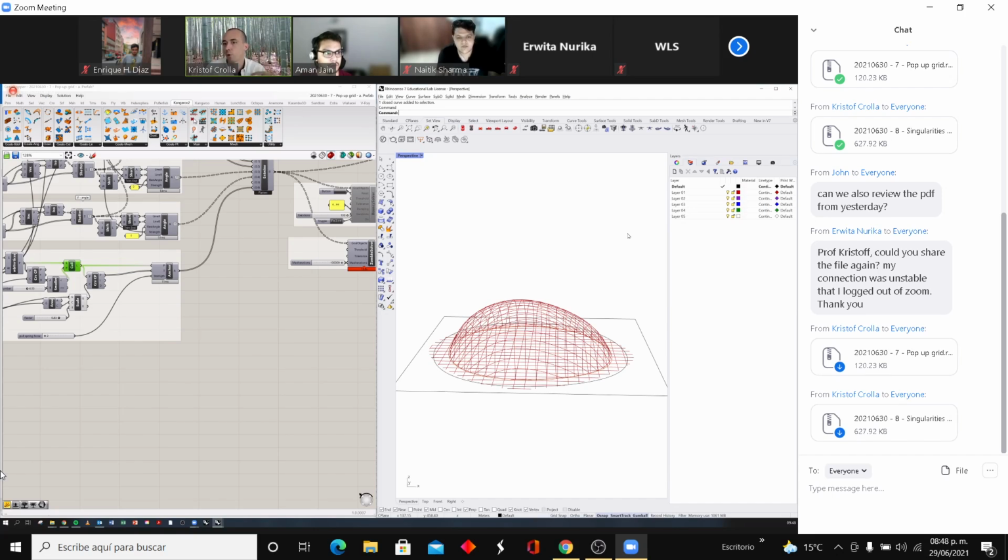You can basically project an equidistant grid on any shape, and if you then put it into Kangaroo, you'll still see that it will deform a little bit, and it will deform entirely based on two things: the topology that you have and the boundary conditions that are anchored in place. So if you change your topology by lengthening parts or by having a denser grid, the bubble shape in the middle will change. And if you change your boundary, then the whole setup will change.